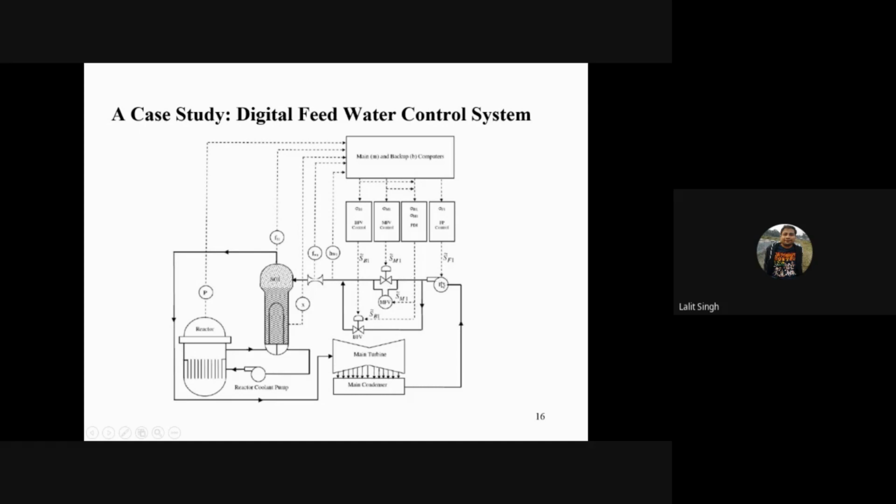to generate the electricity. And not all the steam can be utilized to drive the turbine, so the unsaturated steam comes back. It will condense in the main condenser, and again it can go into the steam generator. So this secondary loop keeps on going. But because inside this steam generator there is water, and it is getting converted into steam, which is basically utilized to drive the turbine,